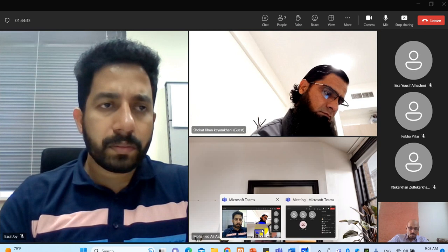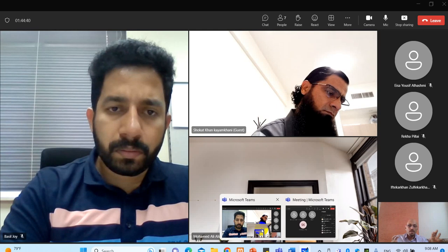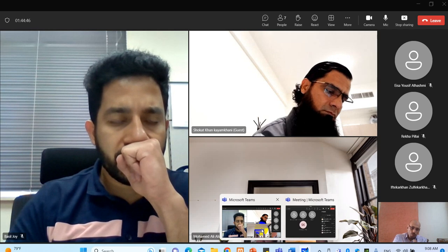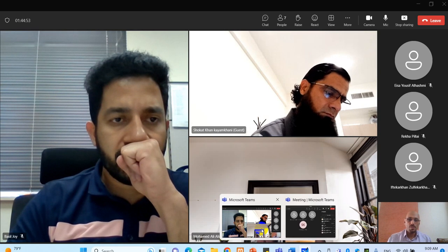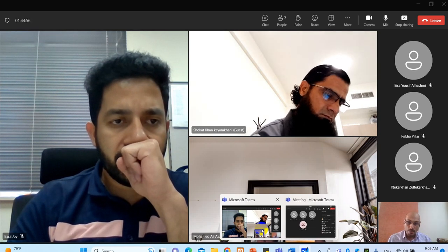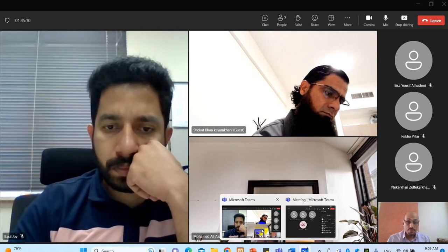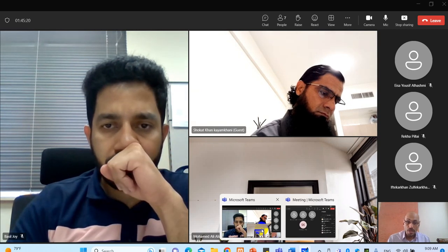We talk about reliability. And you find that GE gives you a graph like this showing how many times you can repair the plates, and it also depends on what time you spend from overhaul to overhaul. Like if you exceed the lifetime of a certain overhaul, like if you're doing hot gas path inspection every 12,000 hours, right? What if you do this overhaul at 15,000 instead of 12,000? You find this component of the gas turbine is exposed to higher stress than design. That makes the probability of failure increase as well after exceeding these 12,000 running hours.